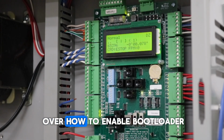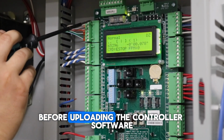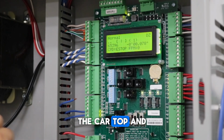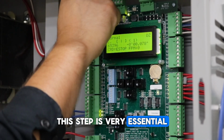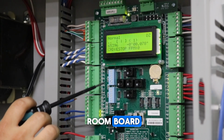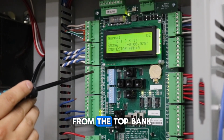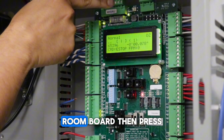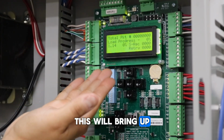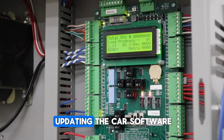Now we're going to go over how to enable bootloader for the machine room, card top, and COP. Before uploading the controller software, disconnect the WD jumper from the machine room, the card top, and COP boards. This step is very essential for the update to work correctly. Next, check the dip switch settings on the machine room board. For the machine room, card top, or COP boards, turn on dip switch A8 from the top bank of the dip switches on the machine room board. Then press the reset button that's located just above the LED screen. This will bring up the bootloader screen. Once the word ready is displayed, you're set to begin updating the car software.